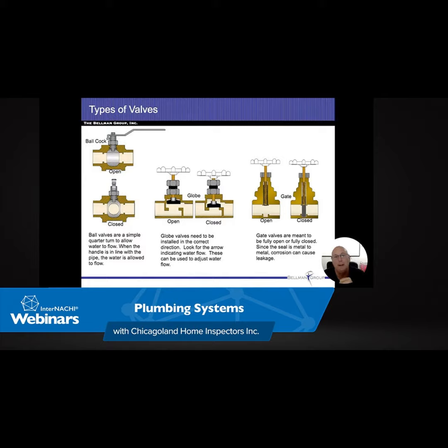Usually there's going to be a screen at the bottom of this pump. And so we want to be careful with the sump pump that there's no debris tossed into it. We want to make sure there's no paper or anything else that could clog this screen up and prevent that water from flowing. Obviously, if it did, then that water is going to come into the house.